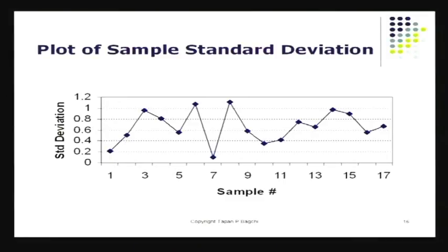This is like one statistic. I calculate a similar statistic called the range, which looks at the highest value in the data collected and the smallest value in the data collected within that sample. The difference between the highest value and the lowest value is what we call the range of the data, of the variation. This range actually is an indication of the consistency of the process. If the process is very consistent, the range is going to shrink down to pretty close to 0. But if the process has a lot of variation, range is going to expand. In some sense, this range is similar to what we call standard deviation, and we'll see that as we go into this theory here.